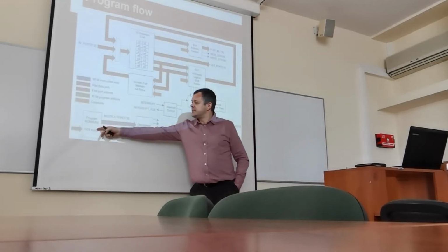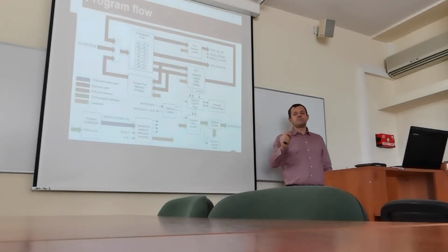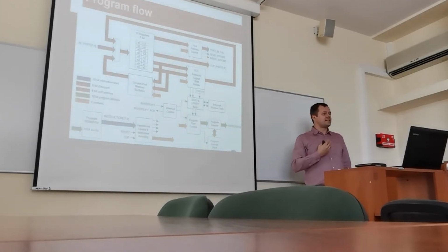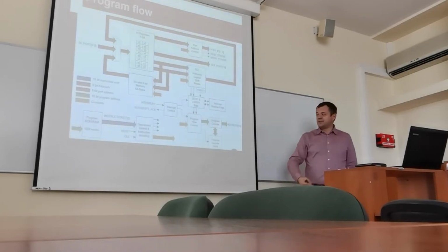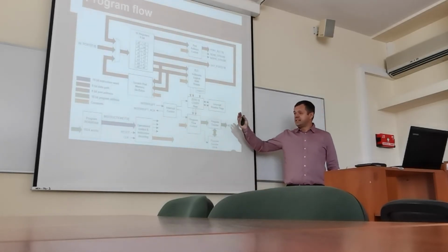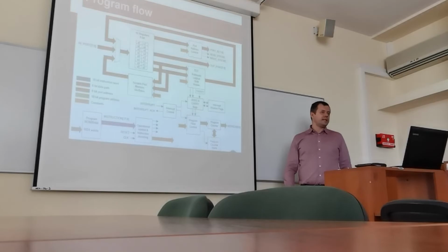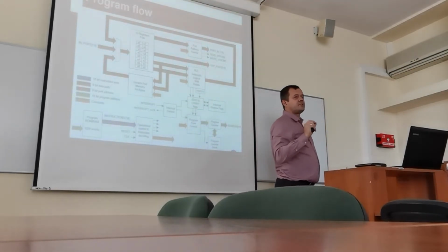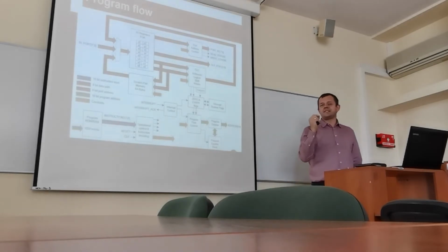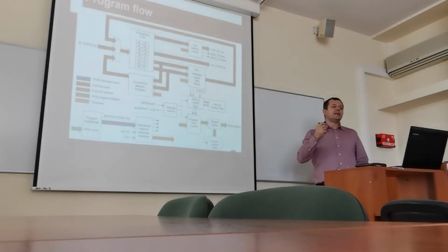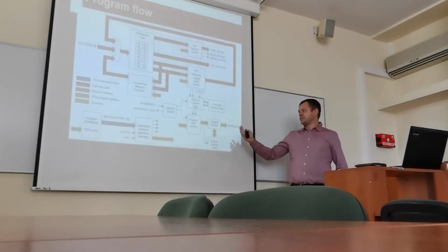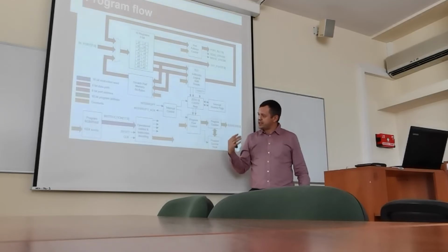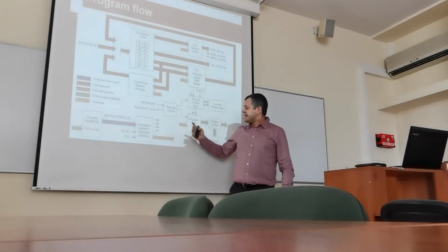And it means that in the program memory, at this starting point, there must be something. When I start with a new processor, one of the first things I do is check the initial value of the program counter. And then when I write the software, I must put something under this address, because this is the initial point. Execution starts from here, because the first instruction that the instruction decoder fetches is from this address.